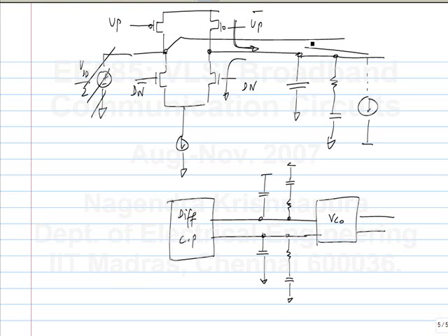No, that is the entire clock and data recovery circuit. Now I am only talking about, see, now we know how to detect phase difference between two periodic signals, right? Our 3-state phase detector will do that very well. It has a range of plus minus 2 pi and the output average is proportional to the phase difference between the periodic inputs.